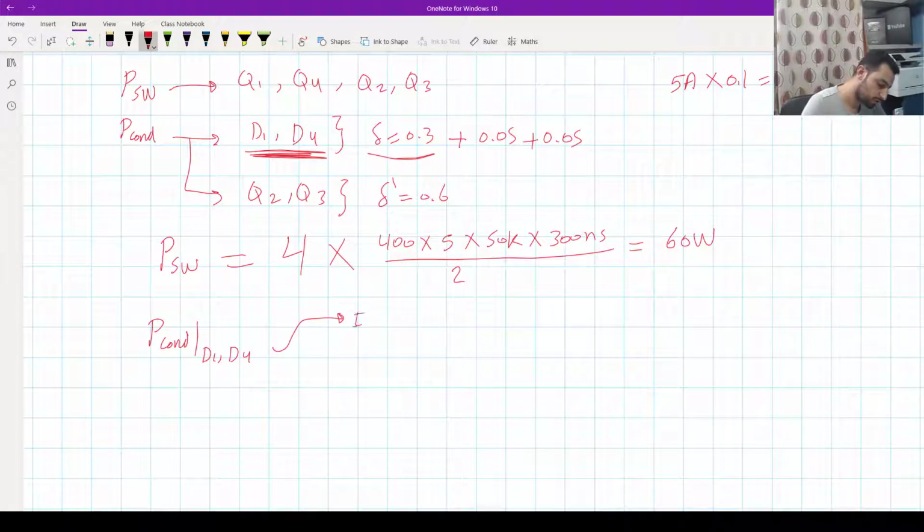Okay, so I average and I RMS will equal: I average is 5 times the conduction time, and the conduction time is 0.3, 30%, because it's not going through the MOSFET, it will go through the diode, the first 30%, and then during dead time number 1 and dead time number 2, we have also flow through these diodes. So in total, they have 40% time. Okay, so that's why we will say it's delta 40%. Okay, and that will equal 2 ampere.